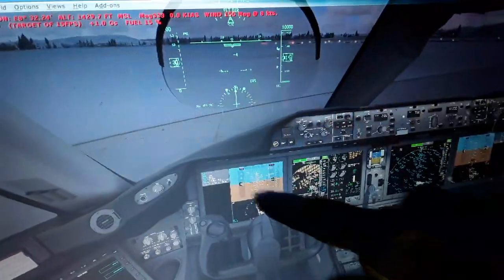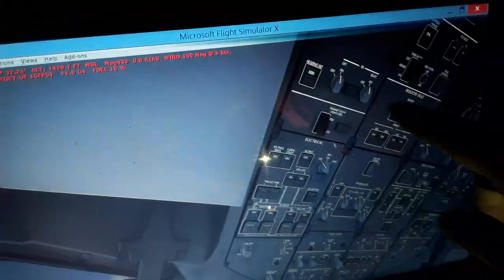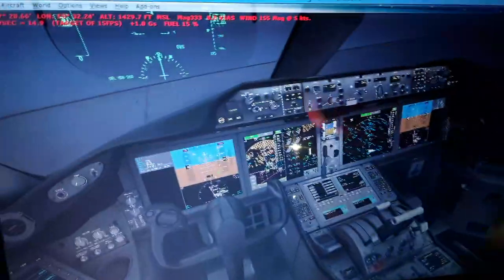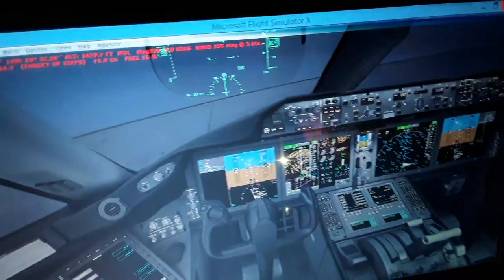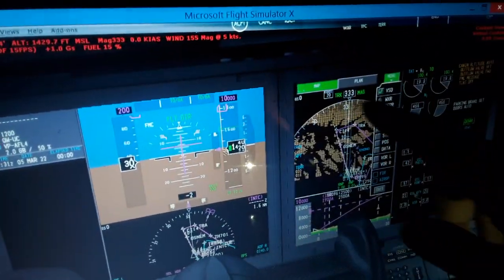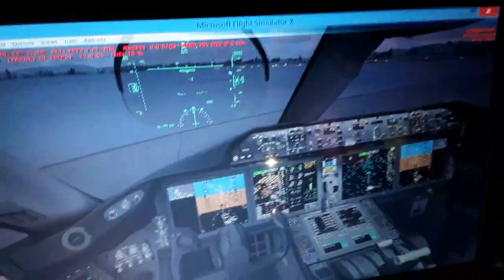In flight you see the altitude indicators display. We have the airspeed, the pitot static, pitot tubes, pitot static, pitot dynamic for the airspeed and the altitude, radio altitude, angle of attack of the aircraft as it flies. So all the air data you see here, and the GPS, 3 GPS receivers, angle of attack of the aircraft. All these are controlled from the air data computer here.